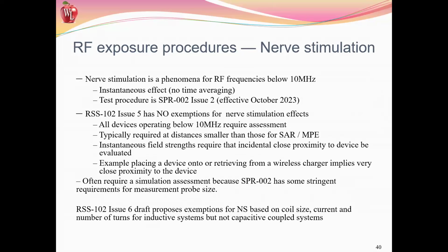Incidentally, you have to have an incidental close proximity device to be able to do the evaluation, because you might end up being real close to the device, for example, a wireless power charger. As you put things on and take things off of that charger, you're going to be in real close proximity.